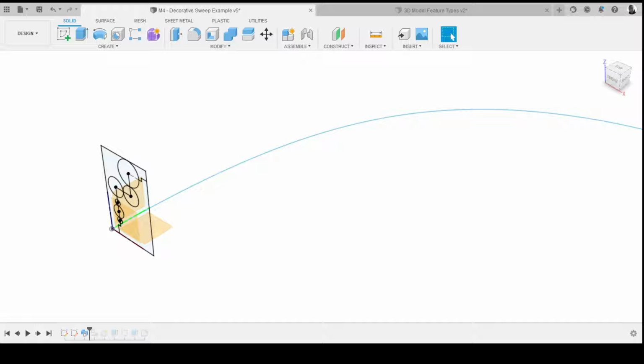The other thing that's really important is that this path sketch and this profile sketch have to be connected somewhere. If there's a gap between where this line meets this profile sketch, Fusion can't jump that gap, if you like. They have to be connected or pierced. Those are the things that you've got to remember to get right in sweeps. Other than that, it's very straightforward.